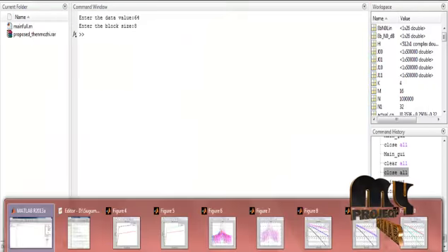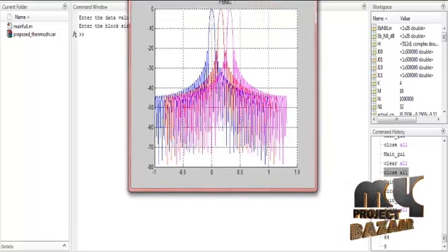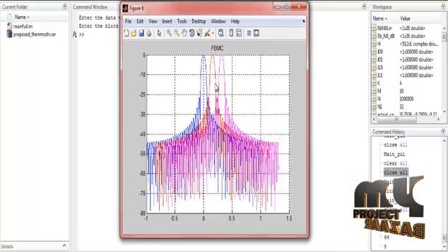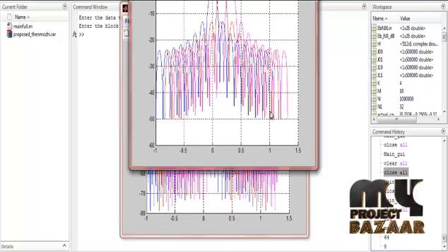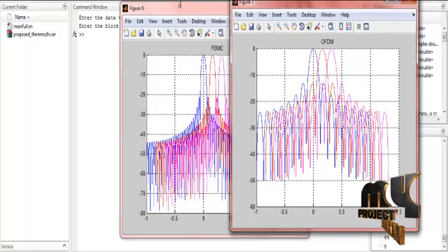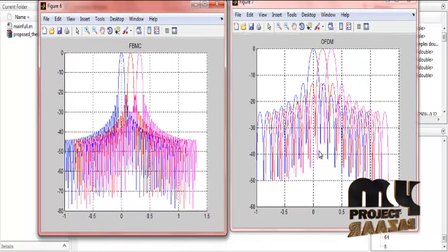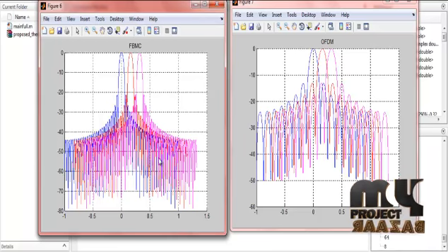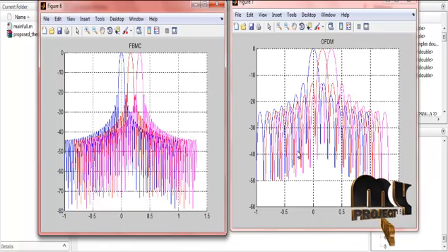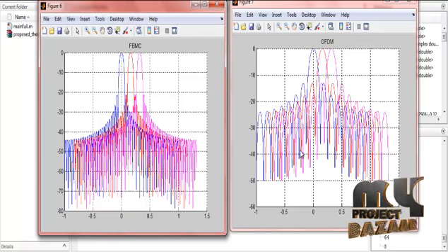In the next figure, this is the FBMC, the filter bank multicarrier modulation. It shows a number of peaks, and then the normal OFDM peak. This is the normal OFDM generator peak. FBMC has a filter bank, so it filters the larger number of peaks and represents multiple curves of the process. Compared to the OFDM process, FBMC is more efficient.